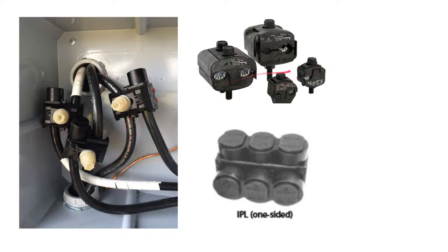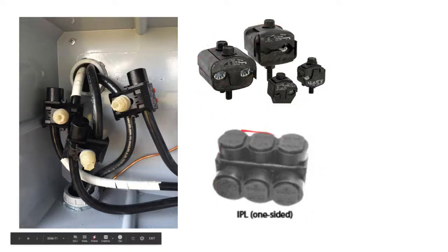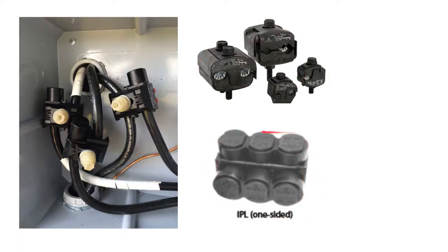Piercing insulating tap connectors were used instead of standard tap connectors because they install faster. Standard tap connectors require cutting the conductor and stripping back the insulation jacket, bending the conductor wire, and other small tasks which require time and hand strength. The piercing insulated tap connectors simply crank down onto the conductor.